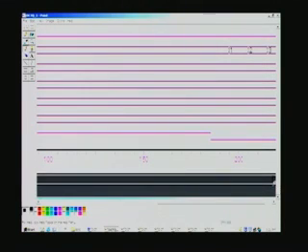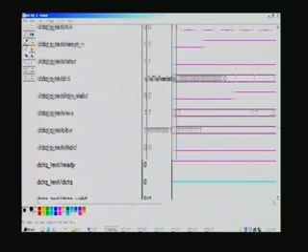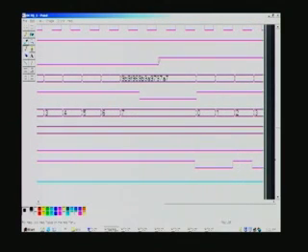And here just remember one aspect here. I think we are starting here, the start pulse is here, that is the third waveform, and it is happening right at this point of time. And although this is happening at this point of time, it will be recognized only at the positive edge. It has missed the clock marginally. So, this edge will be noticed only here, and once it is noticed, the start is converted into another start edge which we have seen in the design, and that will come only one more clock cycle here, and therefore, only at this point of time where this is 0 here is the actual start happening there.